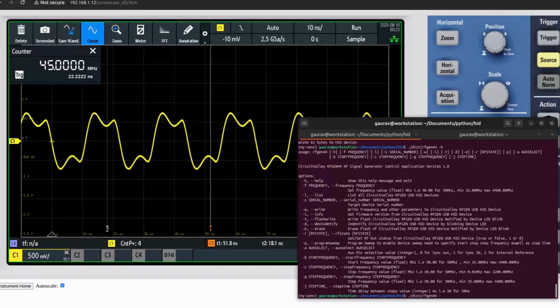So we program sweep by writing P, and you have to specify the start frequency with P. Start frequency 35.0, and stop frequency 50, and you don't need to say 0, but 50. Step is 100 milliseconds. The step value is in milliseconds.